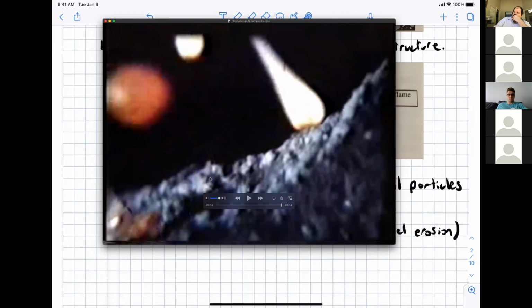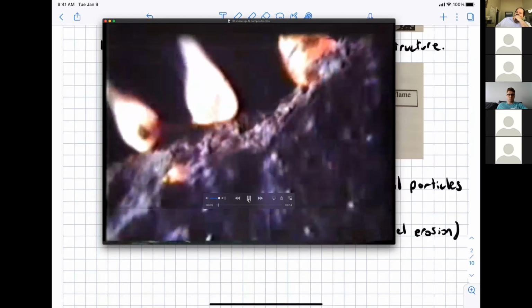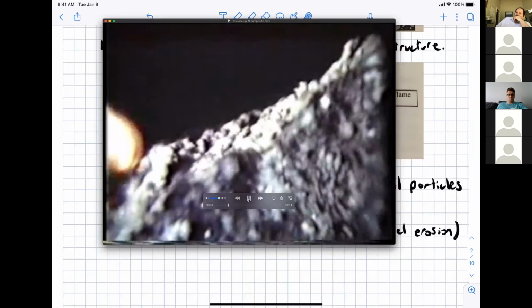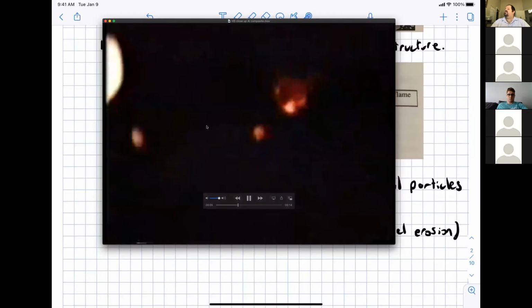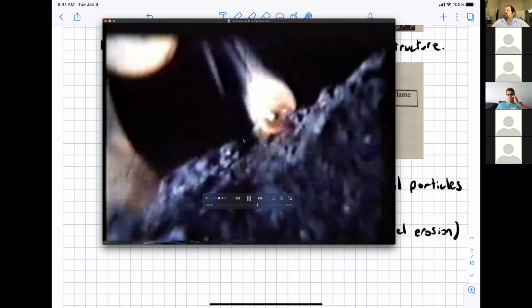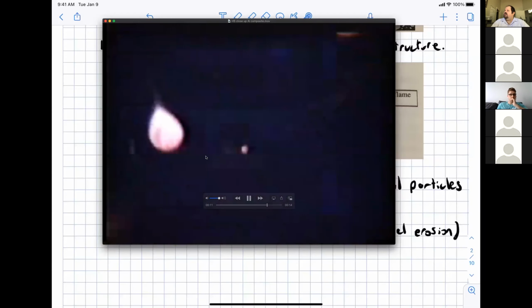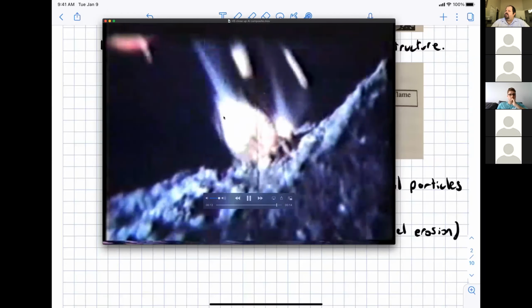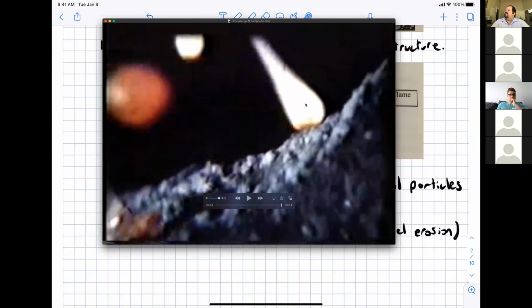And so this is a really complicated process. For a homogeneous propellant, you wouldn't see the richness of physical phenomena, with the melting and merging of these aluminum particles, them lifting off the surface and burning in a standard droplet flame. We will be discussing that in a few weeks, so you'll understand this process too. Okay, and so this is a really, really complex process.